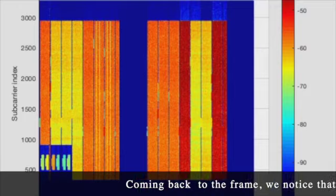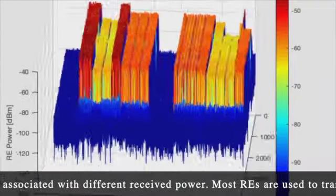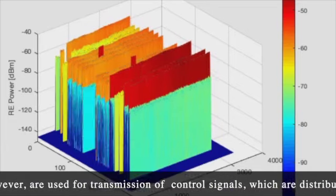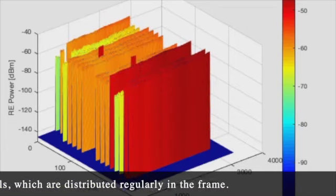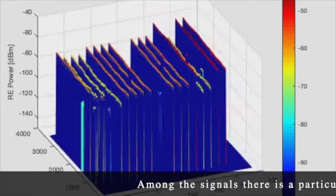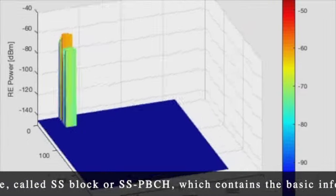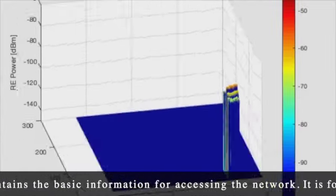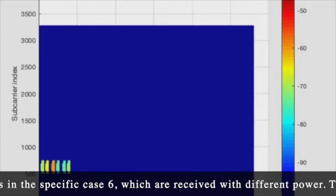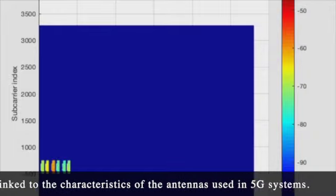Coming back to the frame, we note that REs have different colors, associated with different received powers. Most resource elements are used to transmit user data. Some, however, are used for transmission of control signals, which are distributed regularly in the frame. Among the signals, there is a particularly important structure, called the SS block or SS/PBCH, which contains the basic information for accessing the network. It is formed by a block of signals, in the specific case 6, which are received with different power. This particular structure is linked to the characteristics of the antennas used in 5G systems.